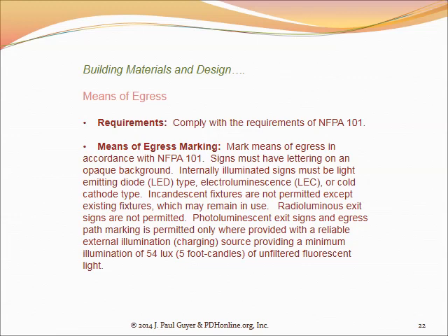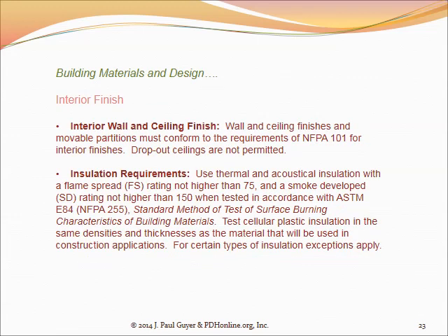They may be visually handicapped, blind, deaf, things like that, and so you need to have other supplementary alarm strategies that will provide, like for deaf people, a blinking strobe type light automatically comes on, and the deaf person sees that and knows he has to leave the building. And then audible alarms for blind occupants. And all of this is mandated by codes, and the principal one that you go to is NFPA 101.